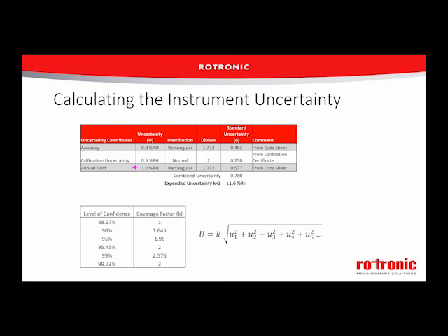So we're dealing with 0.8% RH for accuracy. The uncertainty on our calibration certificate listed it as 0.5% RH, and the manufacturer tolerance for annual drift says it's better than 1%, but since I don't know for this particular instrument what it's going to be, my best estimate right now is 1%. Perhaps in the future, after I have some calibration cycles under my belt, I can look at lowering that or potentially raising it depending on my environment.